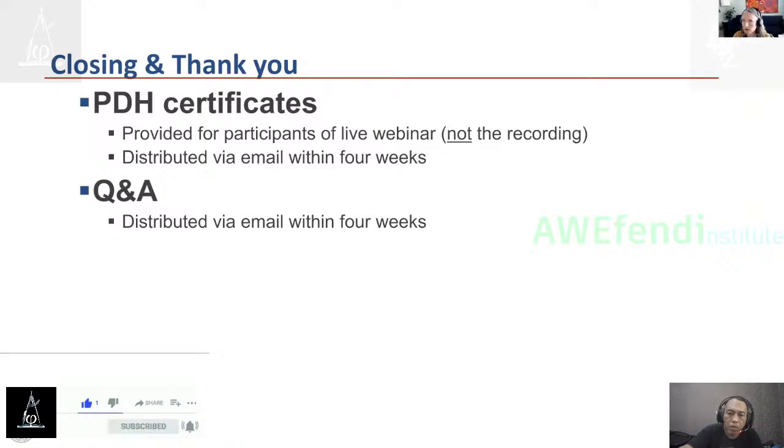So is there anything you can comment about why you would want to use the modal analysis? In what particular cases you'd want to be using it, understanding the findings from P 2012. And there's also been a couple questions about the limitations on using ELF for buildings of a certain height. It says for above 48 meters, and whether there's any anticipated change coming out of the P 2012 findings that might affect the ability to use it for taller buildings.